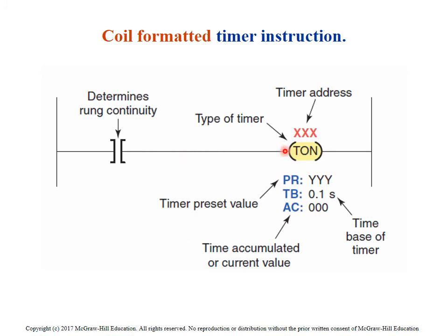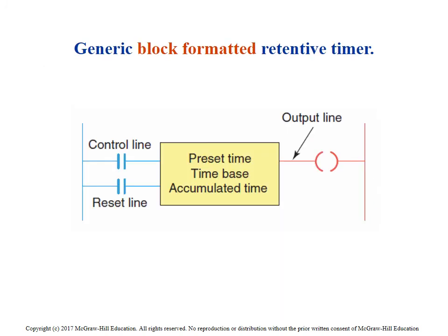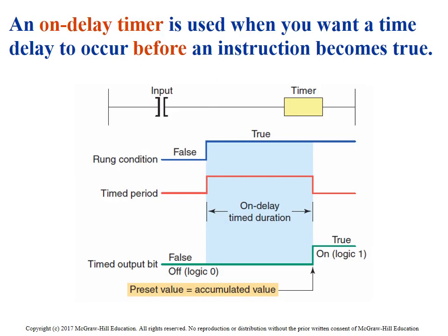This is an older version of a timer. You'd see the little coil that looks like a timer, but it's not, versus the nice neat little box that they have now. Here you've got the address, the preset, the base value that we mentioned earlier that we really won't see in the 5000, and then the accumulated value. Something more along the lines of what we'll see is a box with a timer in the front of it, so let's get to the nuts and bolts of that.